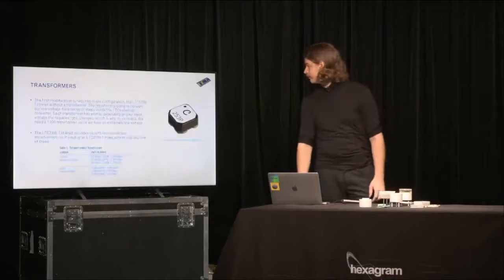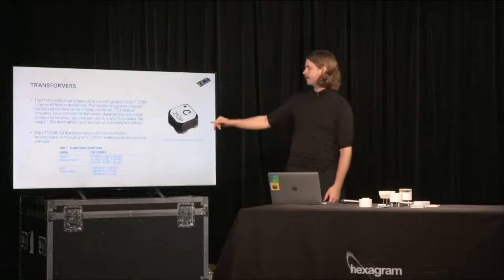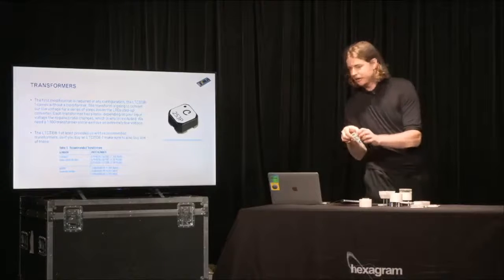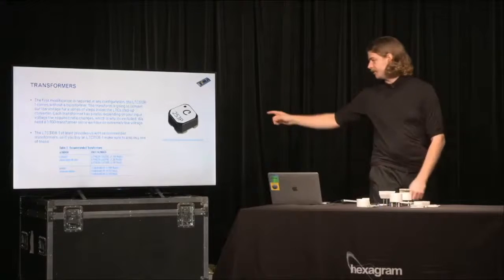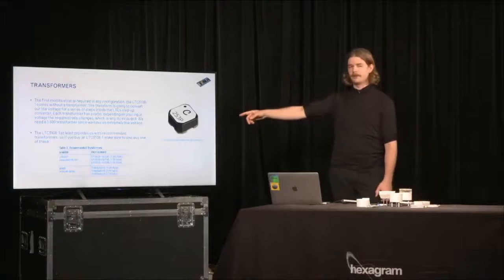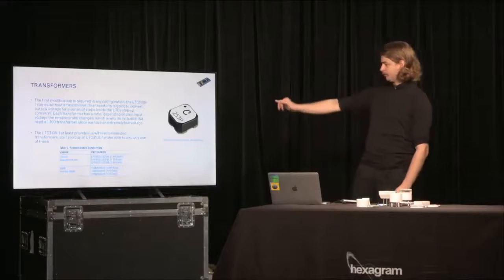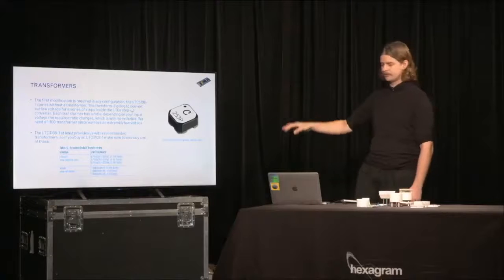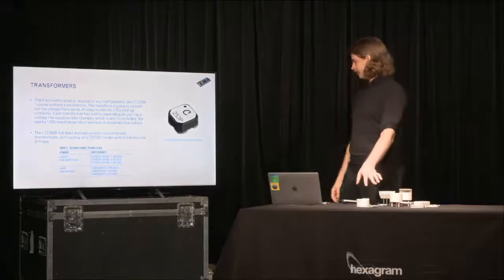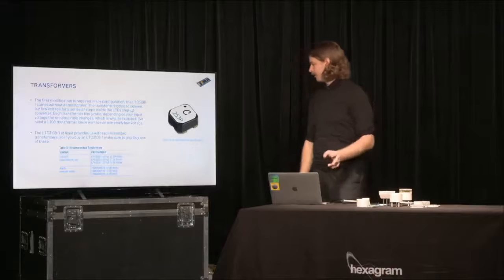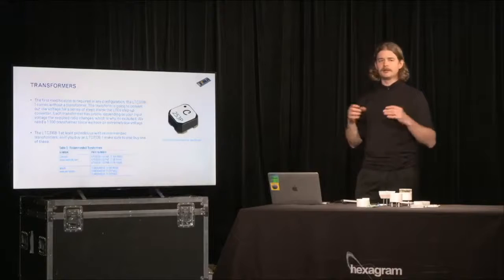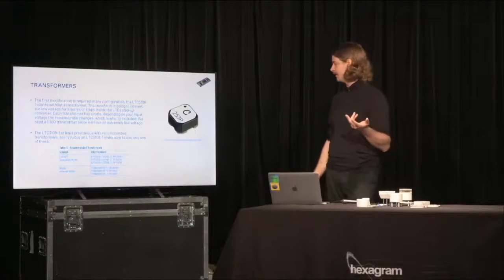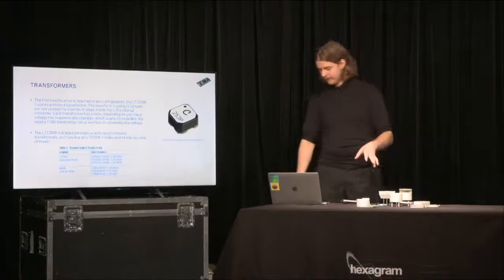So the parts in this, you're going to have to always buy a transformer, which is this tiny little square. You can see it there. Those are the ones that you use with the LTC 3108-1. We're using the 1:100 ratio one. So again, you can come back and look through these sheets if you want to build your own. I did at one point in my research creation want to build my own circuit, open source, to have it available for people, but that's still a ways away.